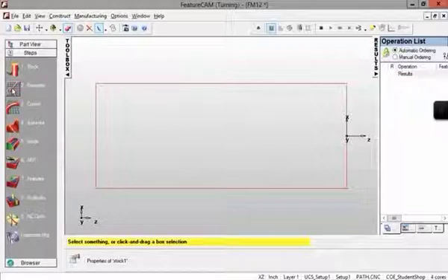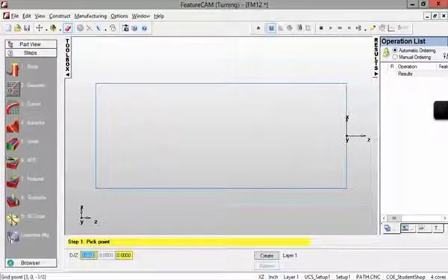And we want to draw the points, and we can click this geometry, the points. I would input these points. You can also find the point coordinates in the lab menu. It's on page 36. Okay, the first point is actually 0, 0. Click create. Okay, it's actually already here, but the coordinates are hidden. Okay, the second point is 0.75 and negative 0.38. Okay, great.